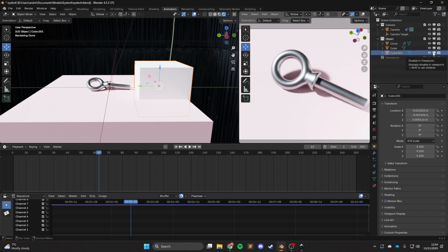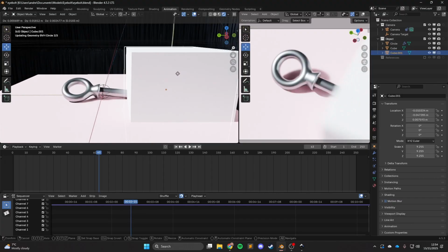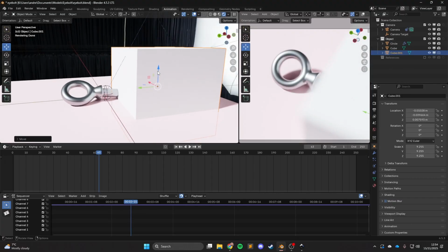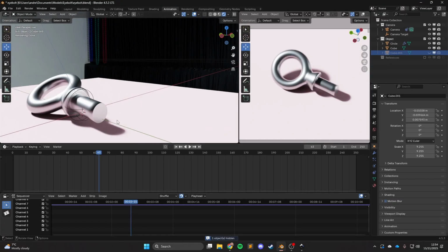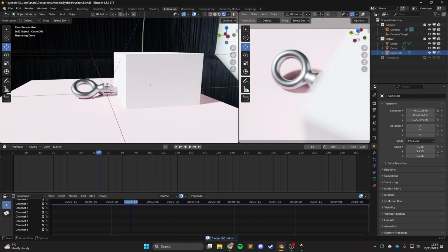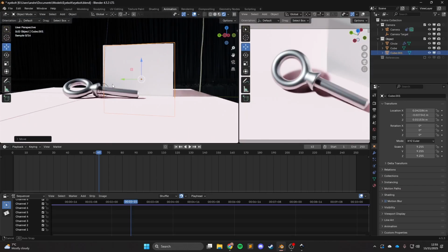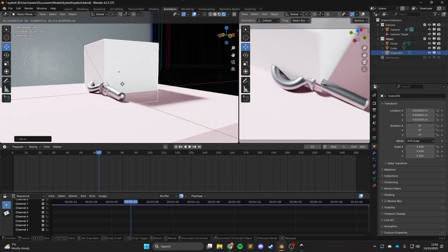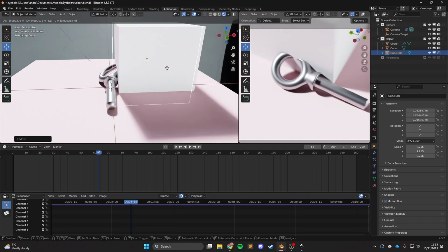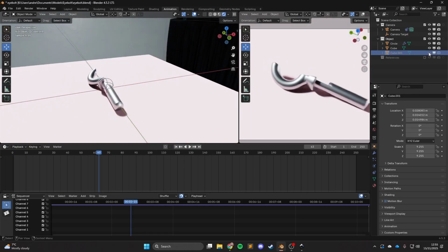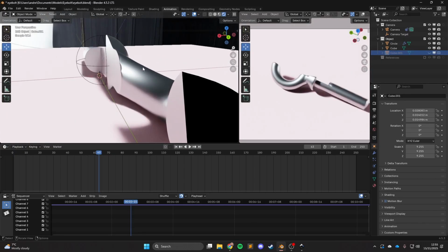If you just make it visible there, or not visible there actually, and then cut it away like that, you can see it's got this cutaway now. And because we've turned off this render setting here, it doesn't appear in renders. And say if you want to make this, maybe there. Again, it's quite slow when you start moving things around like this because of just how Boolean works as a modifier. But you can see here we've now got this fancy cutaway.